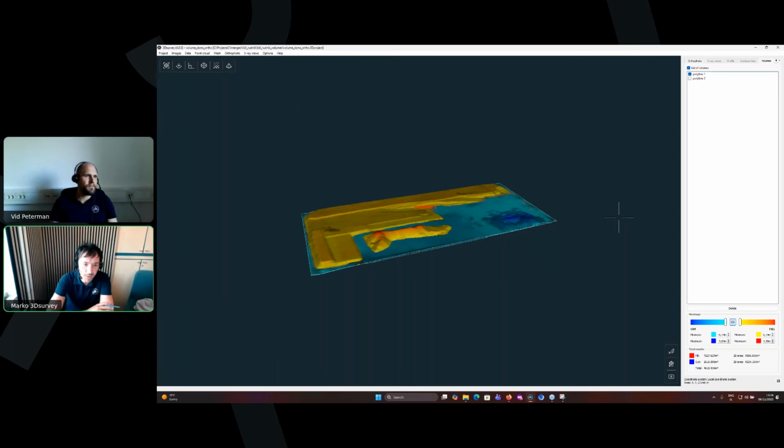Another one, is there an option to use 3Dsurvey 4.0 to calculate a point cloud out of data captured with the DJI L2 scanner without using the DJI Terra in between? Yes. So here the question is where you want to calculate it from. DJI L1 and L2 scanners also have integrated cameras. So if you import those photos into 3Dsurvey, you can create point clouds from those photos.